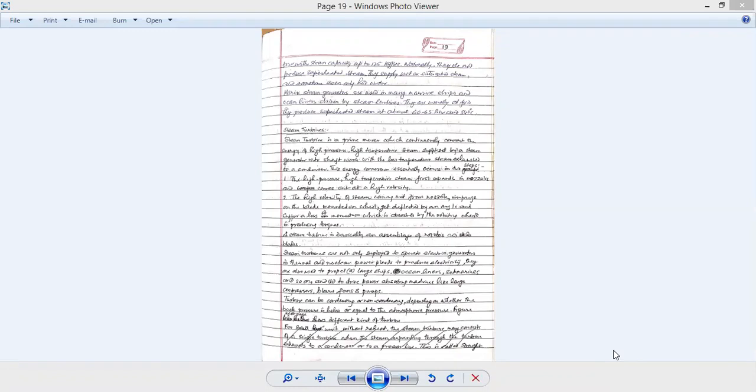This is the definition of prime movers, which are used to generate power, where the movement is created by some artificial means, and this movement is used for generating the power itself by running an alternator or power generator, etc. These prime movers are generally all the turbines, like steam turbines and water turbines. In steam turbines, we use high pressure steam for the creation of movement in the turbine, and in a water turbine, we use high pressure water for the creation of movement in the turbine itself.